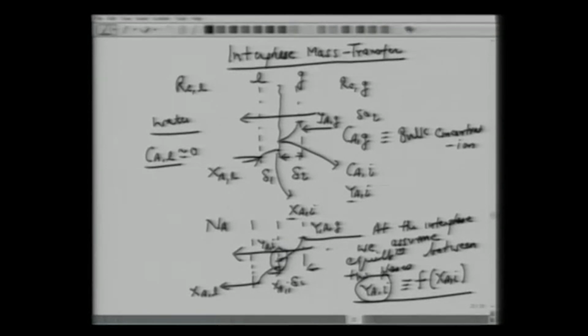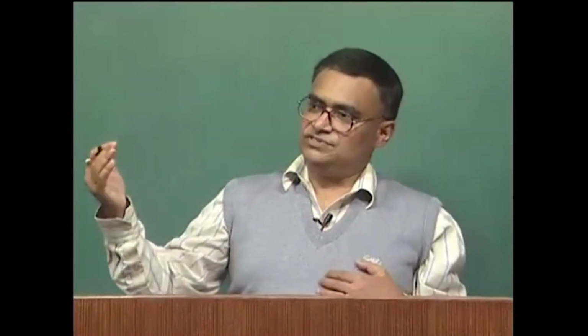Okay. So before we go further into the mathematics of this, let's try to understand that we have defined two concentration levels. One, we have called bulk. When we say bulk, we are assuming that there is uniform mixing, so that we have one concentration level either in the gas phase or in the liquid phase. So sulfur dioxide is 1%, 10,000 ppm. So it's constant at 10,000 ppm. Now we have water, pure water. As the water trickles down, of course, to start with it's zero concentration, but as it goes along, it will get contaminated with sulfur dioxide, which diffuses from one direction to another. However, whatever concentration we have at any level of, say, this absorption column, it's a constant.